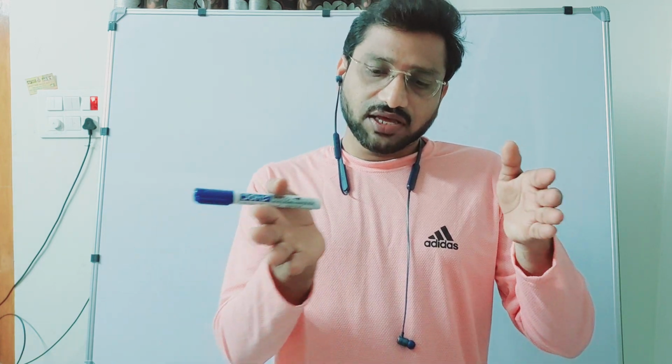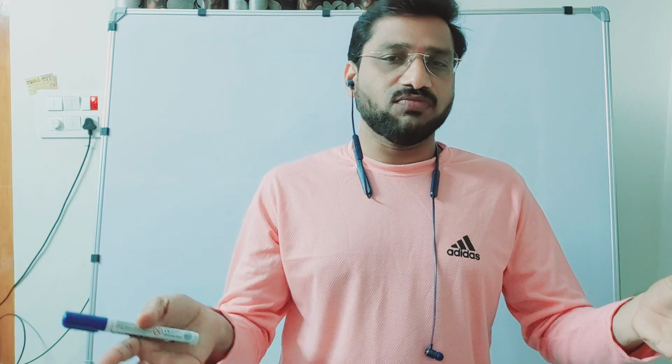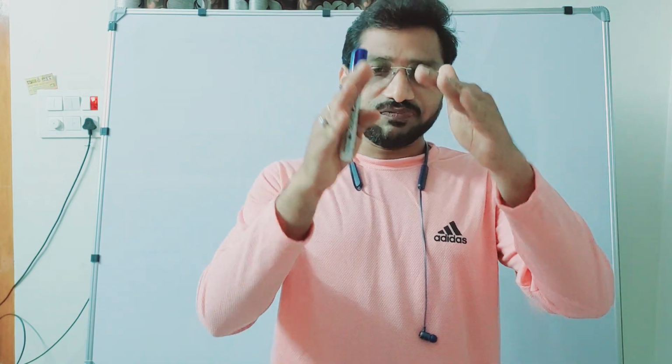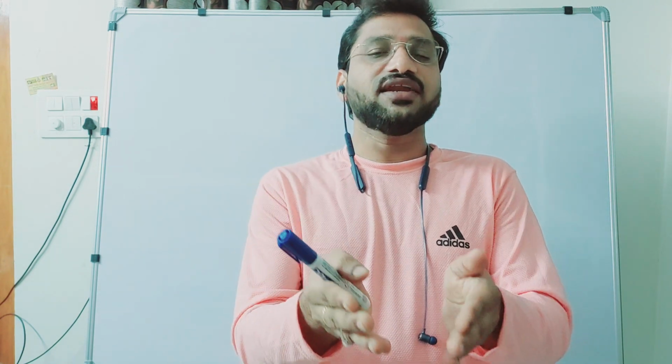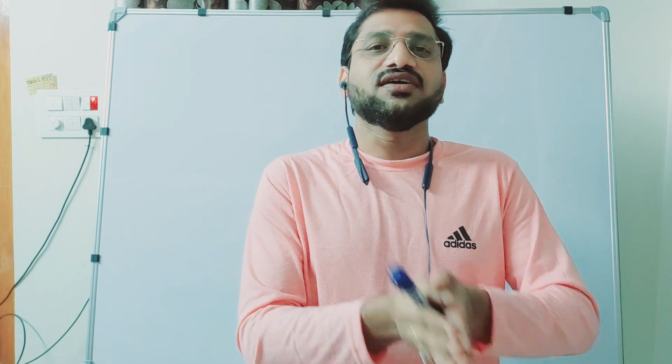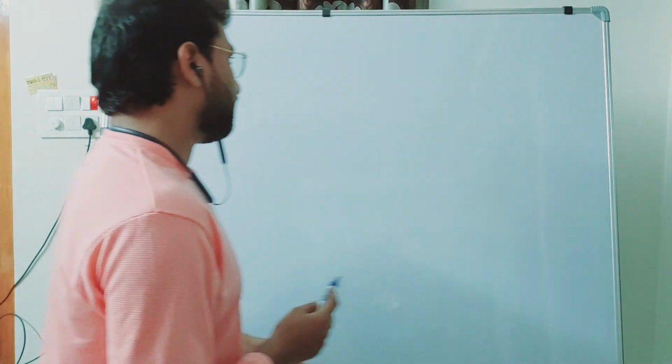Now, if the transformer is to be constructed, these two electrical circuits are to be connected somehow, but not physically. Therefore, a magnetic medium, called a core, an iron core, is placed between the primary circuit and the secondary circuit, and this magnetic core acts as a medium for the induction process. As I told you, the transformer is working on the induction principle but not the conduction principle. Okay. Now, what are the quantities that are maintained as constant? It is very interesting to know.